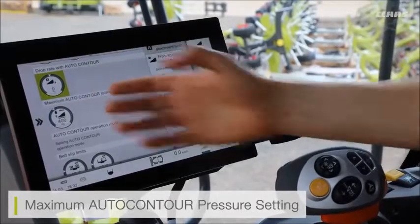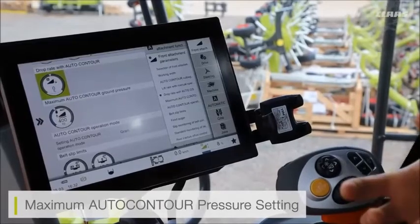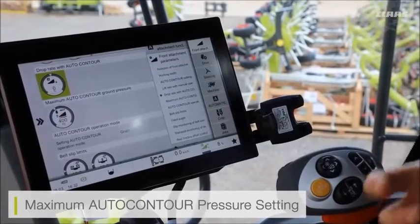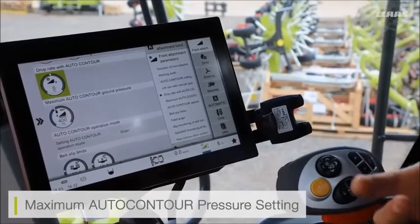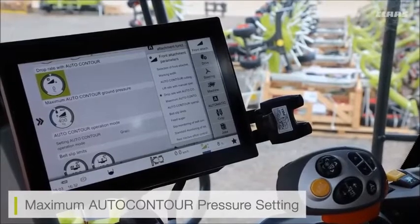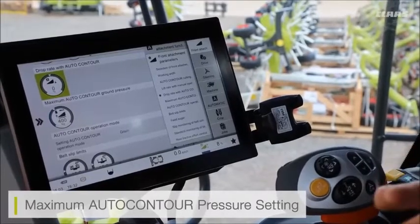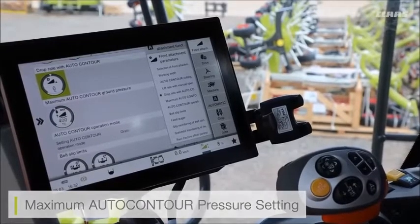However, what this setting is doing is it's telling my cutter bar what is the maximum amount of weight it can put on the ground before my feeder house takes over. So again, my feeder house won't allow my cutter bar to put more than 400 kilos of ground pressure on the floor, so that we're not going to be causing any additional damage to the cutter bar if we do need to be running it straight onto the floor.